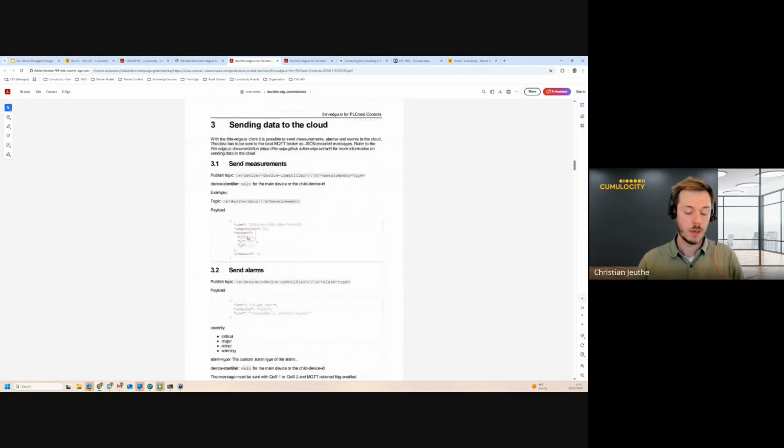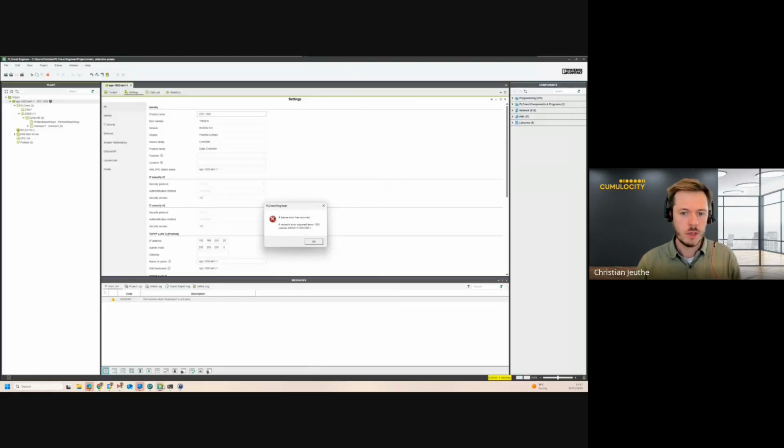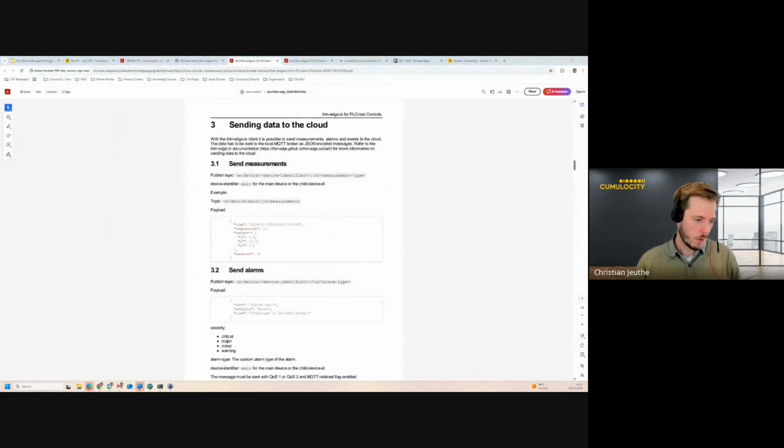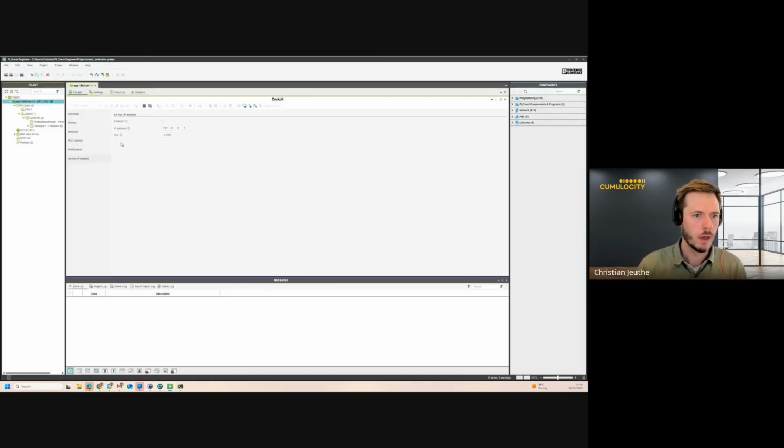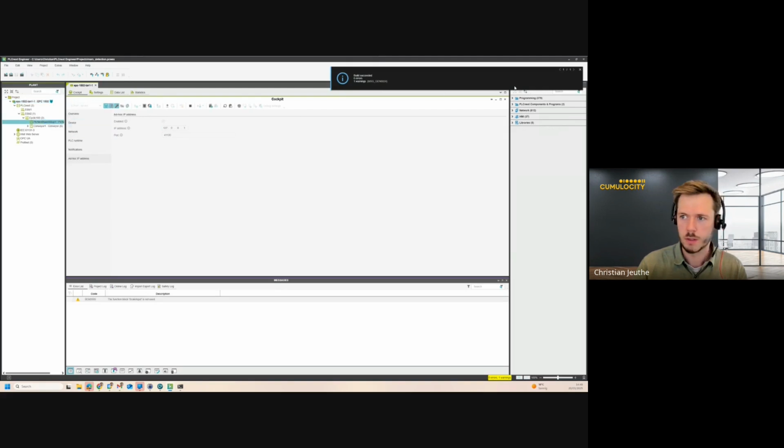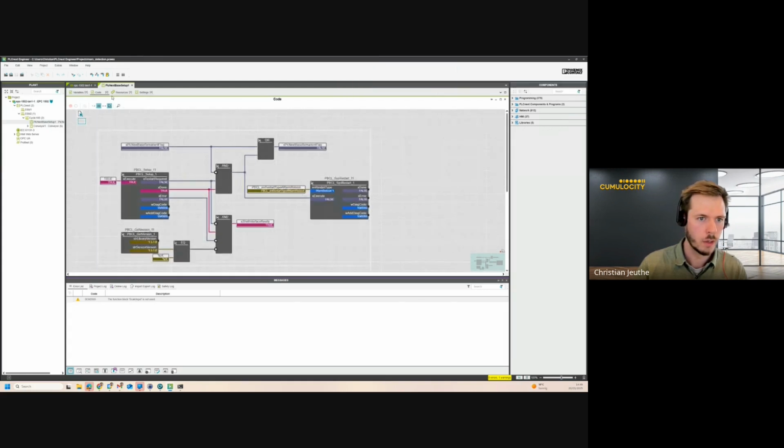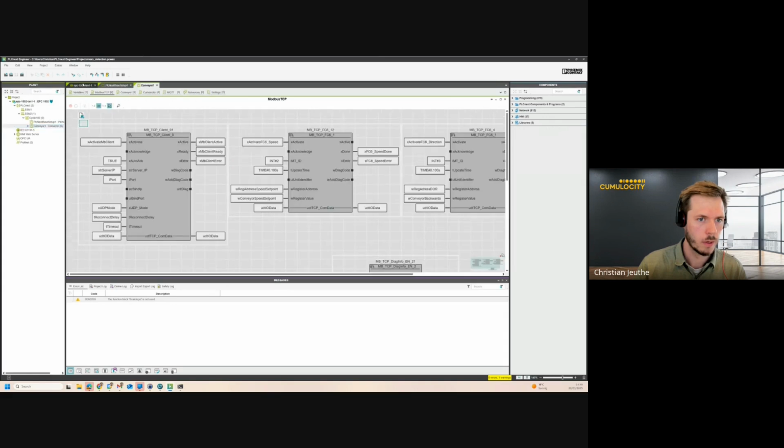Next, it's a matter of setting up the project, right? It's necessary to create a PLCnext Engineer project and define the MQTT connection and to establish the interaction between the PLCnext Engineer and the MQTT broker of ThinEdge. Connect, and then we can actually see what's going on within the device. So we're building the project, and we can see how the connection is being created, right?